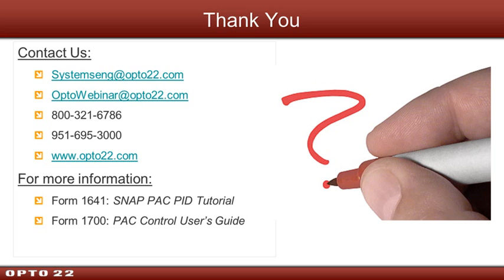So just that answers the question, but just to fill out everybody else, what they're asking is, we already have a physical PID controller, a standalone black box device that has an analog input and analog output, and maybe some sort of interface for being able to set P, I and D. And so what the gentleman is asking is, how do I transfer those settings when I upgrade that black box standalone PID controller to the Opto system? And that's why I said, well, if you can find out what the algorithm is, and if Opto matches, and you can find out the scan time, then you can set up Opto, and yeah, you'll be able to transfer them across. Hence my answer, it depends.